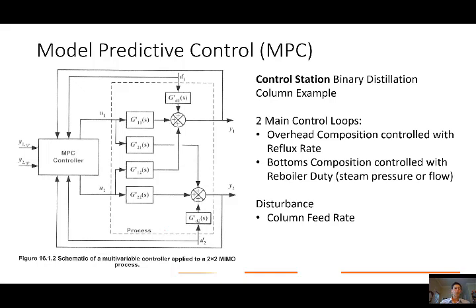And where the multivariable controller fits in the grand scheme of things, such that it can set the manipulated variable position for both manipulated variables, taking into account the set points of both controlled variables relative to their actual current readings, measurements, and take into account any disturbances. You may have talked about two manipulated variable, two control variable loops in the class and decoupling them, and that's one of the things I want you to look at later on. We'll talk about it. The cascade jacketed reactor also has a DMC controller algorithm built into it that I'd like you to play with.